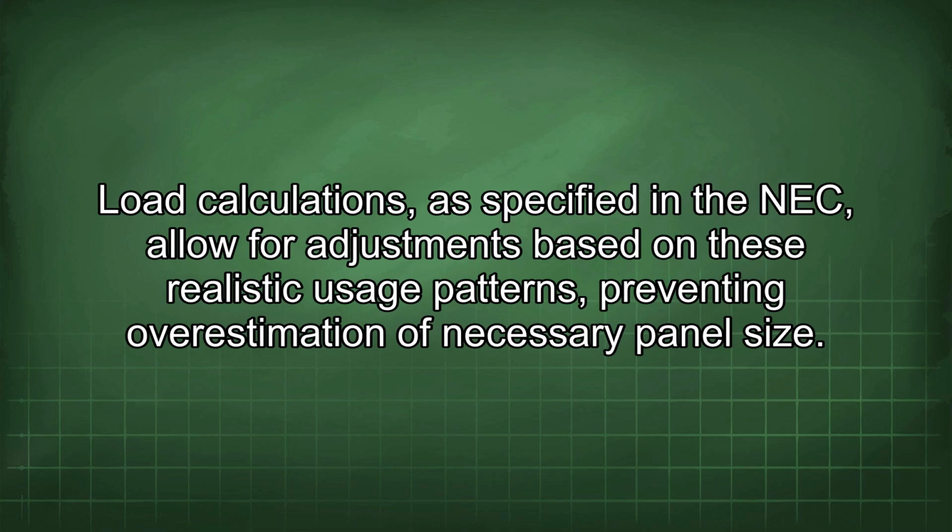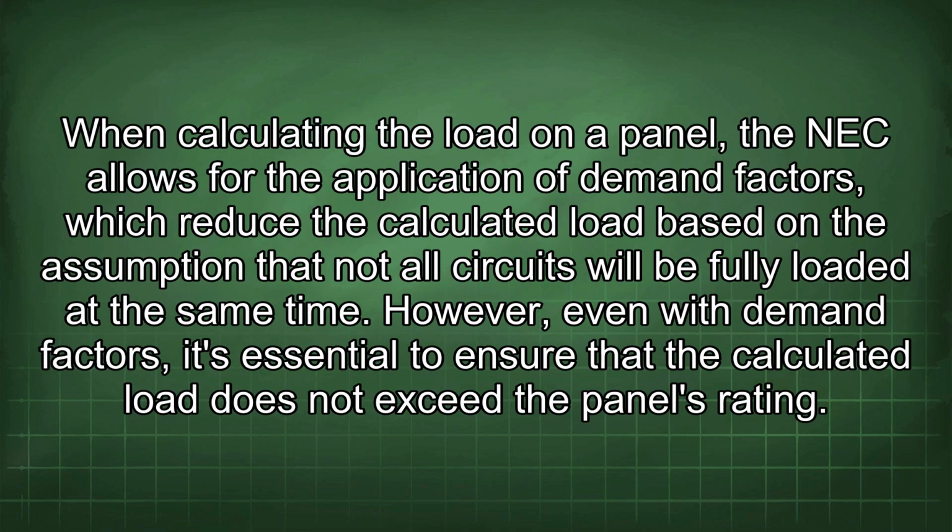When calculating the load on a panel, the NEC allows for the application of demand factors, which reduce the calculated load based on the assumption that not all circuits will be fully loaded at the same time. However, even with demand factors, it's essential to ensure that the calculated load does not exceed the panel's rating.